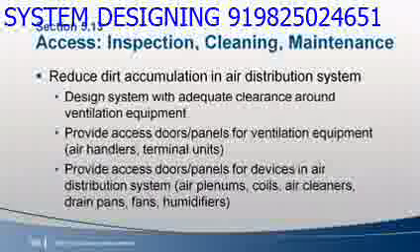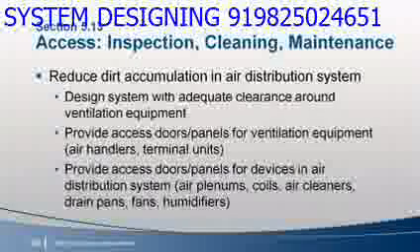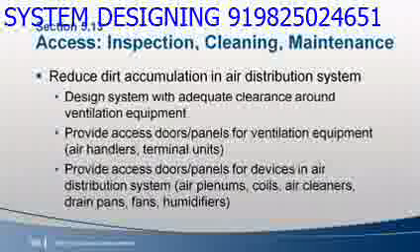It requires access doors or panels to allow for cleaning, routine maintenance, or calibration of air system components, such as coils, filters, drain pans, fans, and humidifiers.